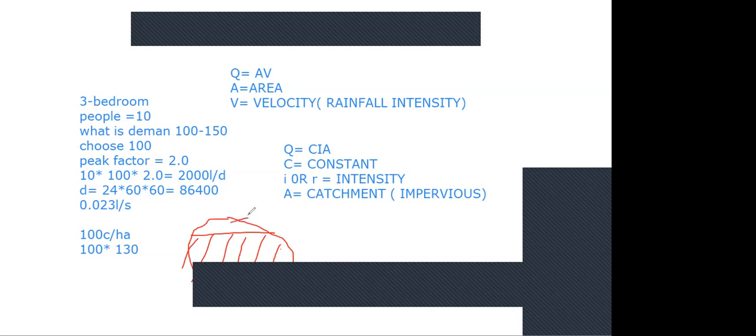So here is 10%. The code says you should give small space, because if you flow full, if there's any surge or any water hammer, the pipe will rupture. So normally the standard says 0.7 to 0.9. Your design water level should be between 0.7, which is 70%, to 0.9, which is 90%.